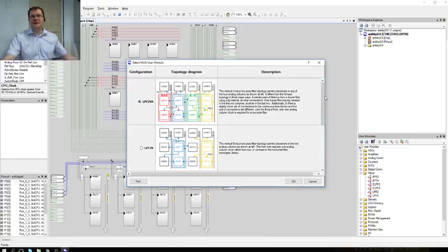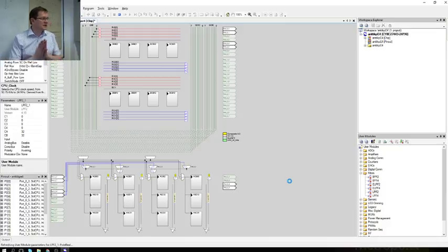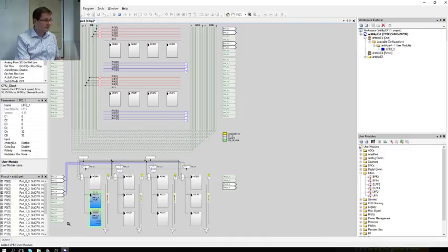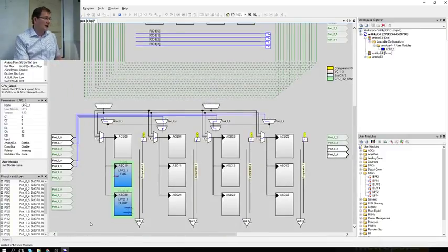Basically the difference is how the digital blocks are used. This one is as good as any. It's a vertical filter topology, and there just click OK, and this takes 2 analog blocks, no digital blocks.